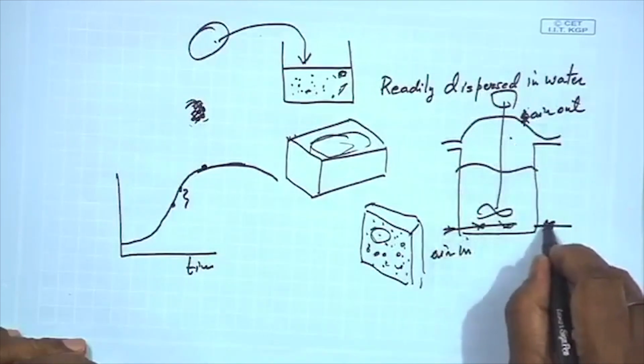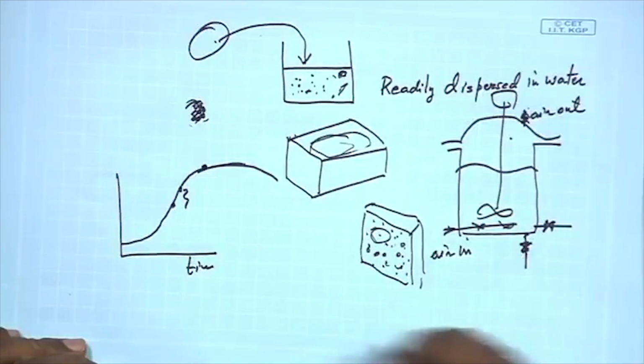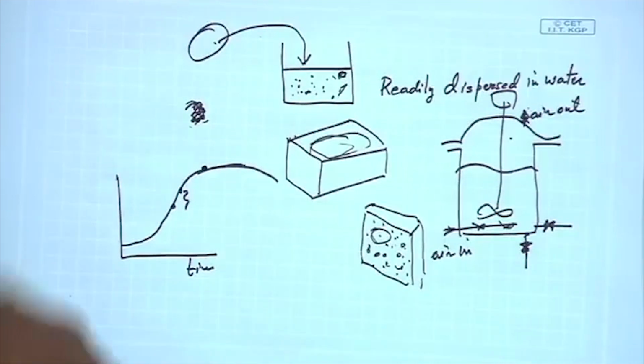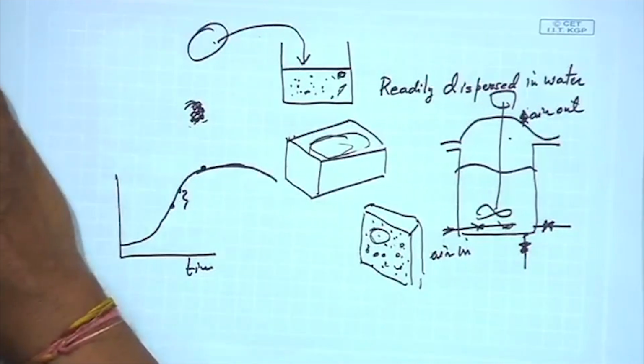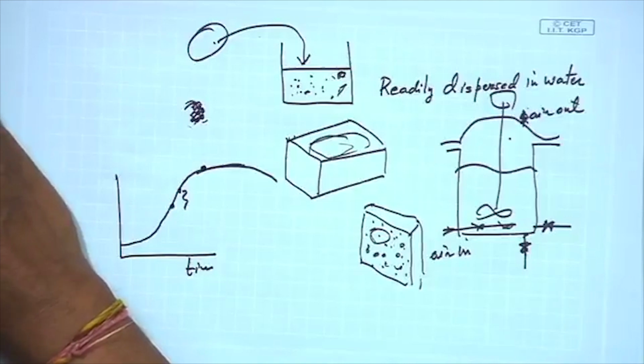Then there will be the manhole, which might be at the bottom. The media is taken through the manhole, and at the manhole we have a gate valve. I have already shown you what a gate valve is, what a globe valve is, and other types of valves. This gate valve is used in the case of the manhole. Then steam is passed through for sterilizing the media. The seed culture is added. Then the temperature of the media is controlled at 24 to 30 degrees centigrade. This fermentation is done in batch for 12 hours.